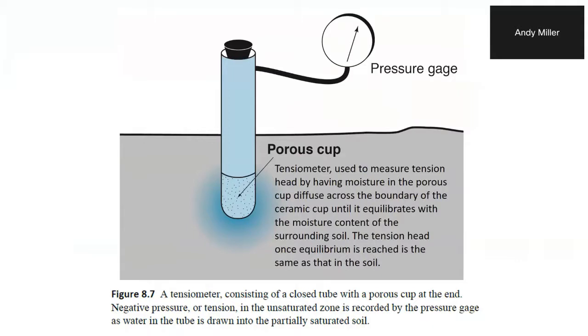And so to the extent that properties of the soil, antecedent conditions and moisture conditions affect the transfer of moisture into the soil, they can also determine whether moisture does not get into the soil and winds up running off. So in fact, infiltration and soil moisture understanding is critical to understanding what actually generates runoff.